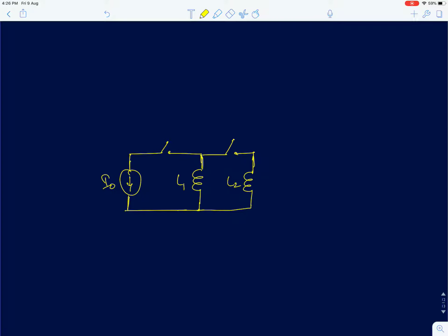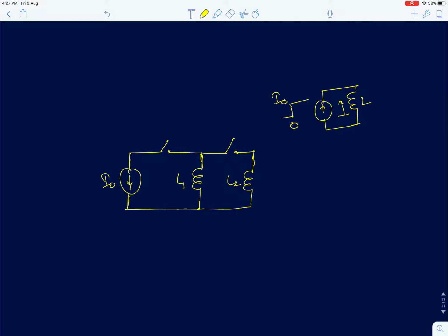Hi everyone. In the previous lecture, we discussed inductors. We then discussed the process of building a current in an inductor. We said that if I had an inductor and a step current of I0 is applied across it, then it develops an impulse of voltage and builds that current I0 instantaneously. But we said otherwise, the current cannot change instantaneously across an inductor.